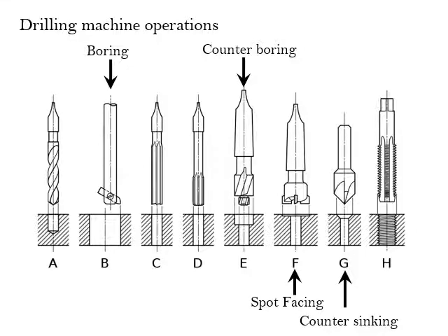Spot facing means you first make a hole on that component. On the topmost surface of the component or workpiece, you use a spot facing tool. A very small amount of material is removed from the topmost surface around the drilled hole. It is called the spot facing process.